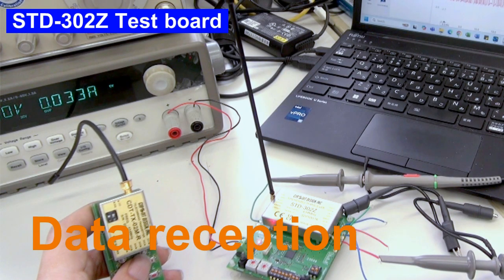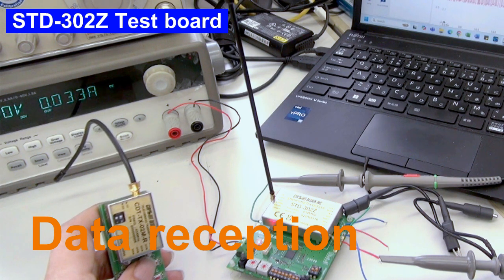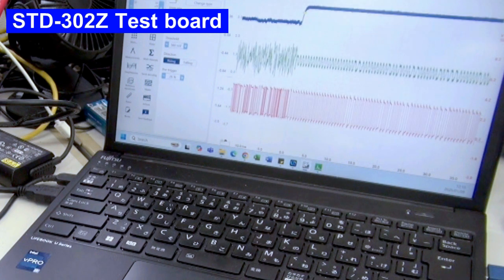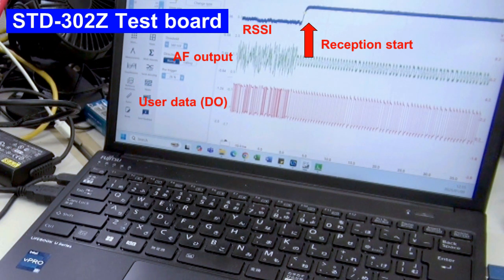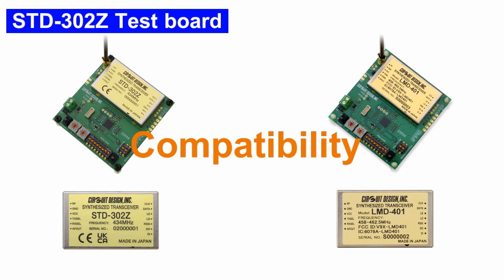For data reception, we can use a transmitter. The RSSI goes high, indicating the module is receiving on the correct frequency. The demodulation can be clearly seen on the AF output. Through the slicer, the data is output on the DO terminal. The test board is compatible with the STD-302Z and LMD-401 radio modules.